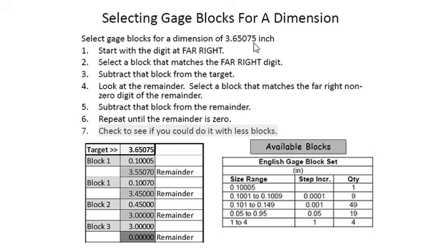And you're going to find in your gauge block box a block that is going to match that last number, okay? Oh yeah, we found one, that's a 0.10005, okay? So that's your block 1. And subtract that from your total height, you will get 3.55070.